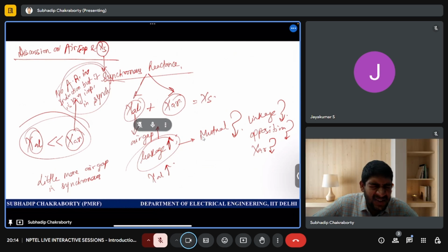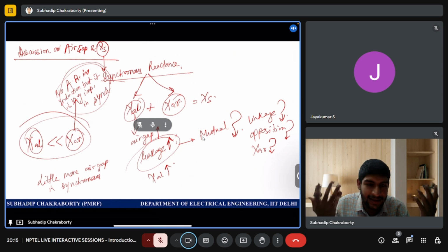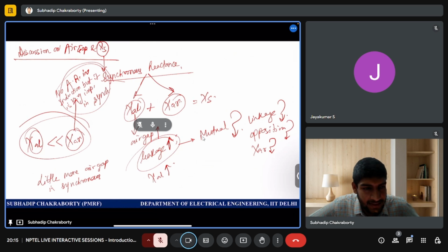Reducing coupling, we talked about it in the induction machine, that purposefully we built a lesser air gap so that most of the coupling happens, more EMF gets generated, and then more torque we can get, because more flux linking with the rotor in an induction machine generated more coupling and more torque.